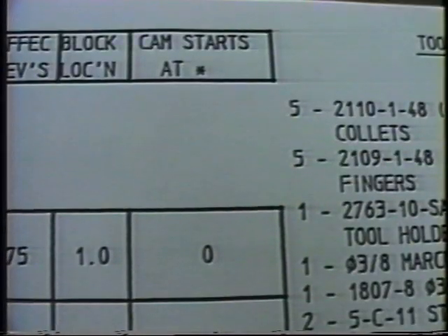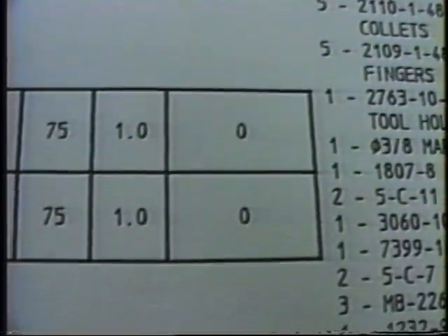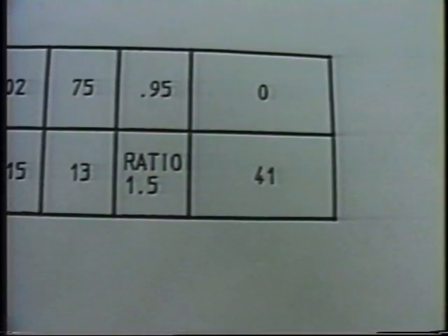Layouts supplied from Davenport starting in 1991 will include a column entitled Cam Starts At. This is the working cam hundredth the tool contacts the material. This number is used in conjunction with a timing system that is mounted on the chuck and feed cam. As this is a new feature on Davenport automatics, we have included a retrofit package with this training program.